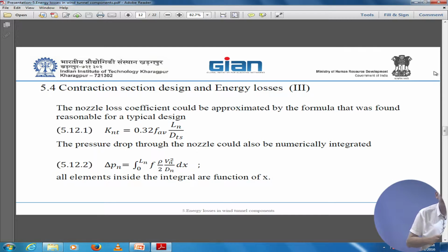So it is not a mechanism to attenuate turbulence, but just because it is straightening the flow and decreasing the size of disturbances, it will decrease the turbulence level anyway. But this is not a mechanism or a method to reduce turbulence. Later on, you need the meshes, the screens.